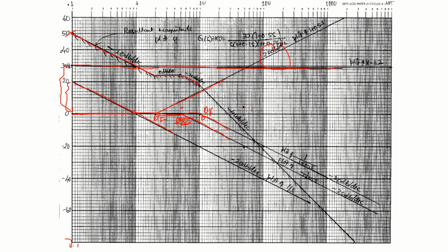That is minus 20. From here another line is starting whose slope is minus 20, minus 20, minus 40. Minus 40 dB per decade. Join those 2 points and no more lines are there, just produce. That is what will result in the magnitude plot. Of course, at each point we can apply the correction factor and get the actual plot.